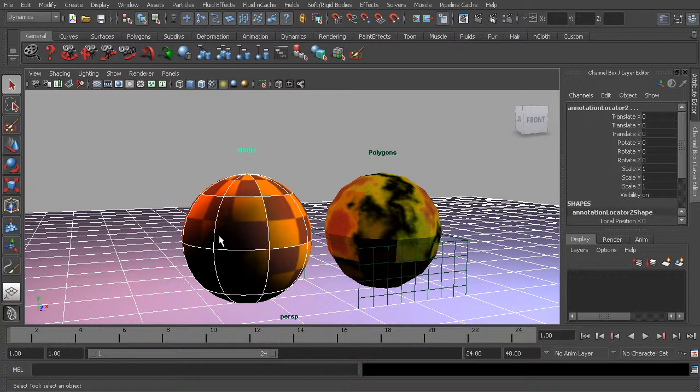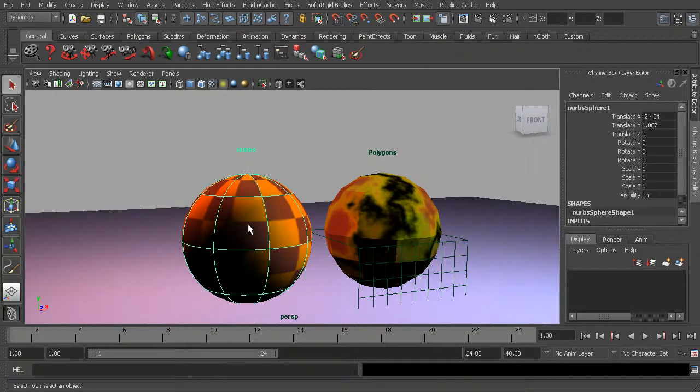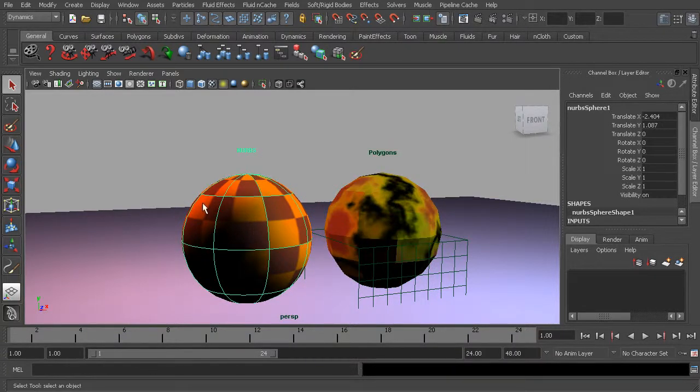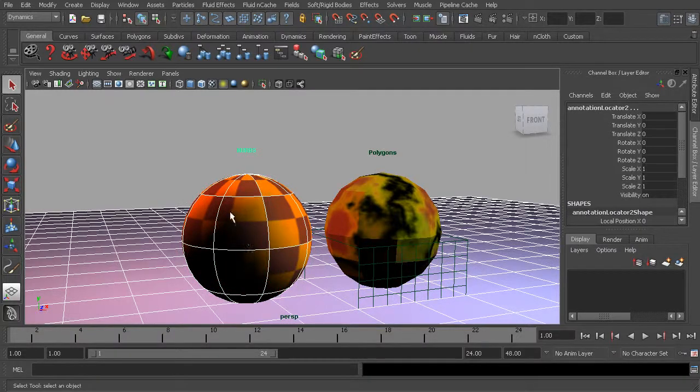Now there's pros and cons to both methods. Number one, with this simple clicking method, it's a little bit more precise. You don't have to worry about accidentally selecting things that you don't want to. With this marquee select, I've known a lot of people who tend to use this as their default selection method, and it's really not a great habit to get into because you can accidentally wind up selecting things that you don't want.